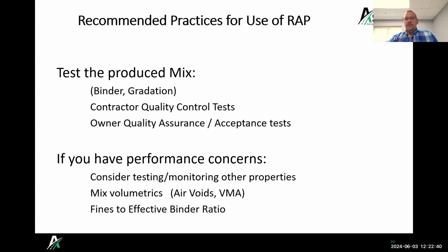Really, maybe then you should consider testing or monitoring other properties, mix volumetrics, fines to effective binder ratio, different things like that. I think wrap got a bad rap, so to speak, when maybe people weren't really testing the mix. They didn't really know what was going into their mixes, and maybe they had a bad performance and blamed it on the wrap.